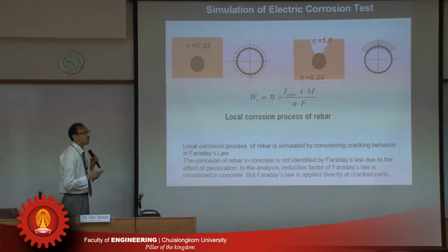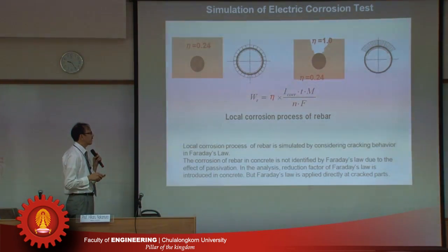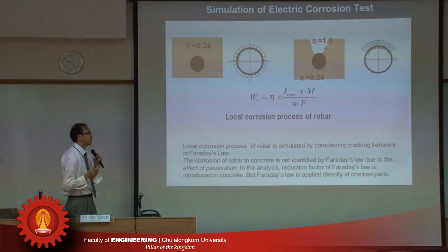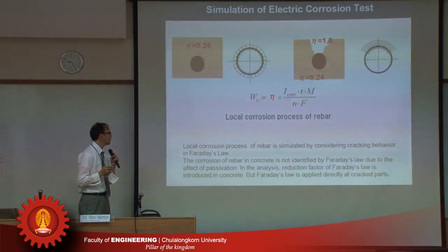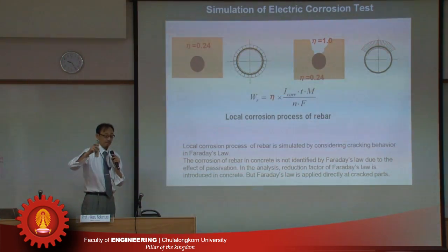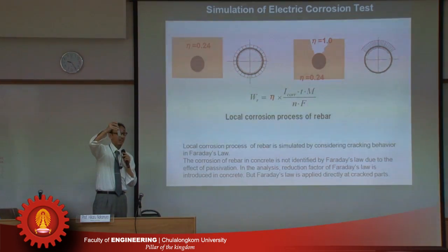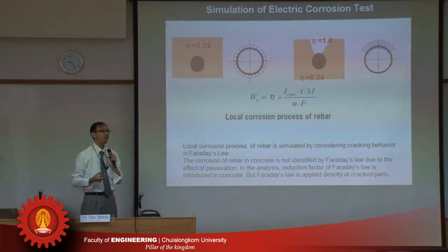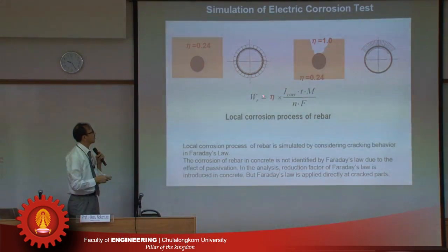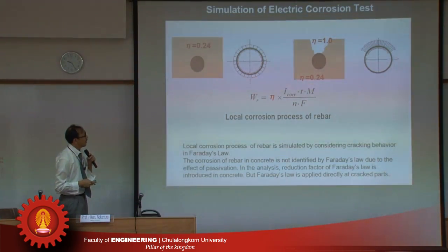But it is known that the corrosion of rebar in concrete is not identified by Faraday's law due to the effect of precipitation. Faraday's law can be applied in the atmosphere, but in concrete it cannot be applied directly. So we consider a reduction factor to account for the effect of the surrounding concrete.